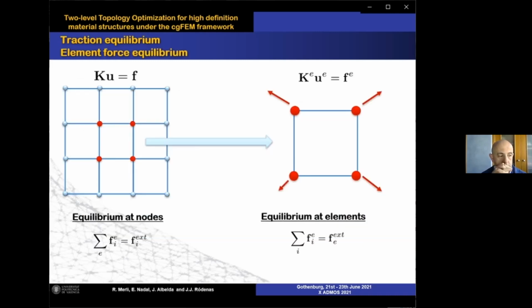Well, which is the idea? First, I perform the finite element analysis of the full structure. Then I can obtain what are the nodal forces in each one of the elements of the big structure. Then, since the forces are in a global equilibrium, it is possible to know which are the forces applied to each one of the elements.